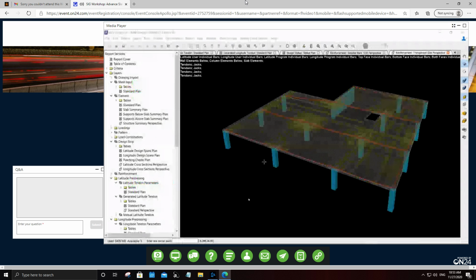So that was the goal that we have taken. With that, I'll use the same slab that was not passing the design at certain points and throw it to the program and let it analyze as many permutations and combinations as it wants, and then give me the most economical design possible with my parameters included. It's also important to let you know that because the program will try so many combinations, it is not possible on a desktop application. So what I need to do is send this to the cloud.